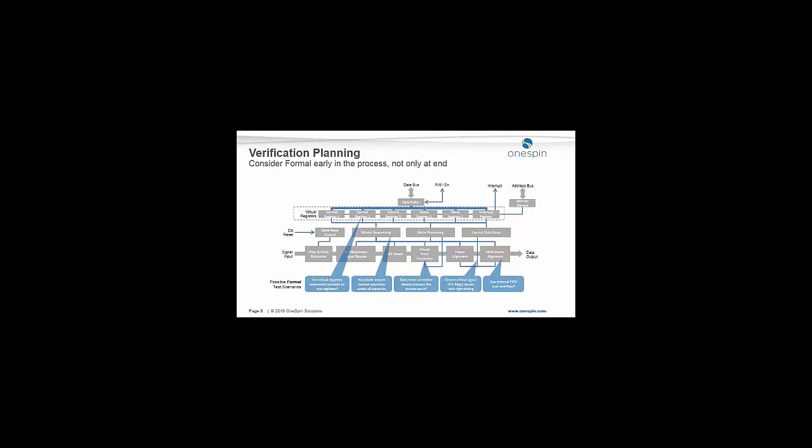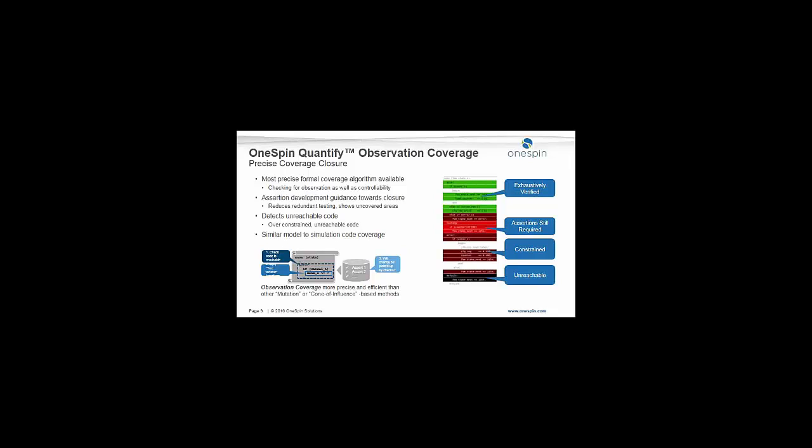You've got some registers in your design. Are the registers actually connected properly according to the IP-XACT specification? There might be some key blocks that are extremely important that you might want to verify with formal to a much higher degree than you can with just simulation. You might want to ask certain questions on the design, like, does a certain signal behave exactly the same under all circumstances, and with the right timing, or about certain events that shouldn't happen. Can a certain FIFO actually overflow, and show me what needs to happen to make this happen? So these are the things that you could ask at the verification planning stage and then ship out to formal.